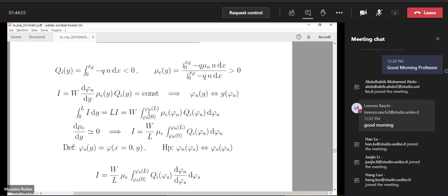And we found out in this analysis that mobility depends on temperature, on the dopant concentration, and if we are near a surface, it depends also on the interaction with the interface, with the surface. So we can analyze these three aspects.